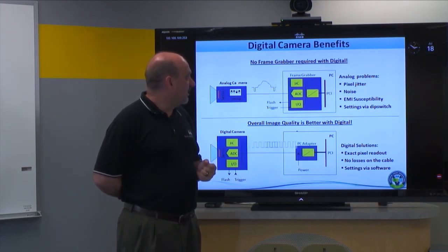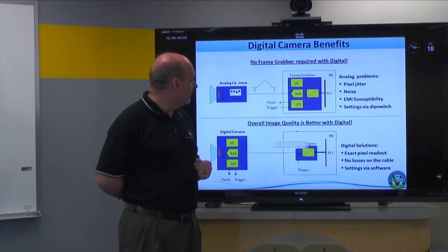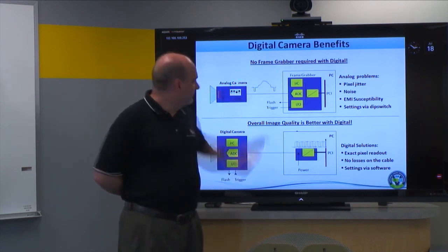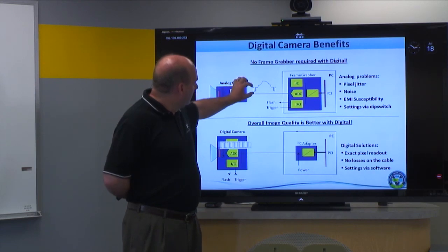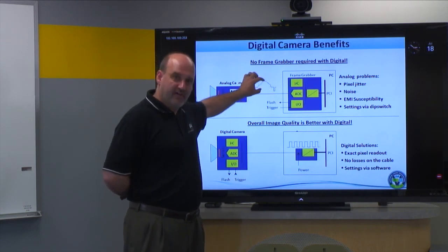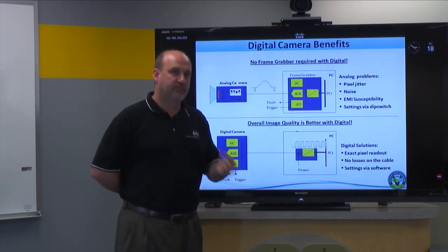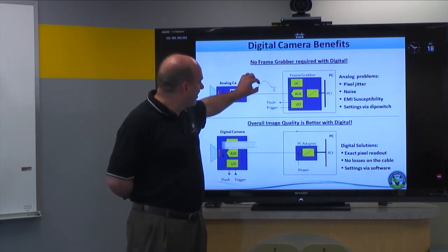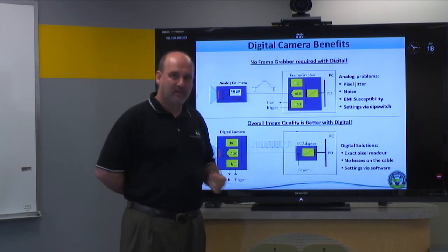Noise and EMI suppression go hand in hand, and an analog signal, by the standard, is a 1 volt peak-to-peak signal with approximately 270 millivolts of sync. That means that just over 700 millivolts represents the entire analog portion of the signal. As we saw again in section 1, the pixel intensity is being converted to an analog blip that is represented somewhere on the horizontal line.